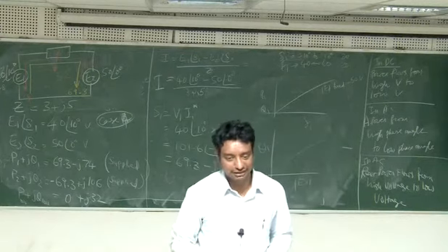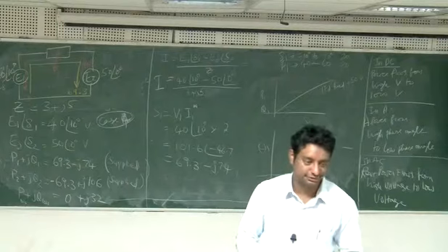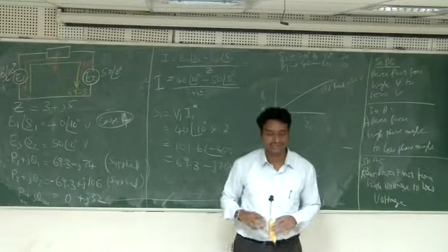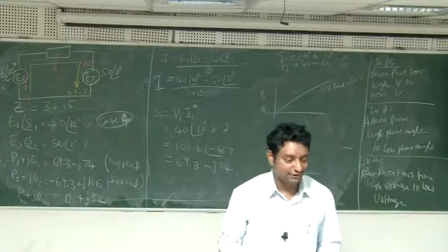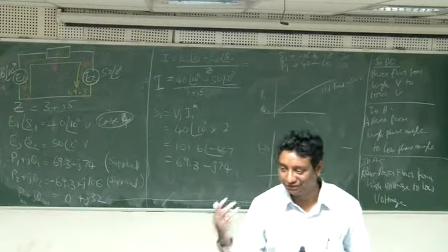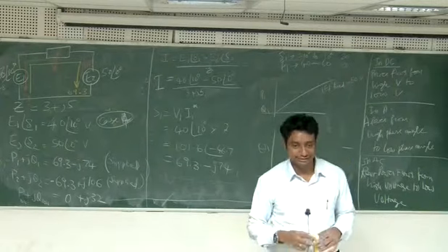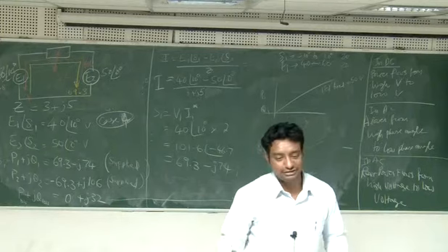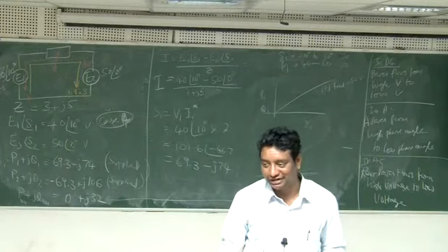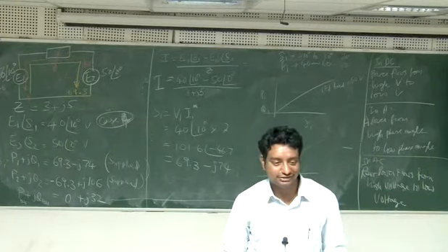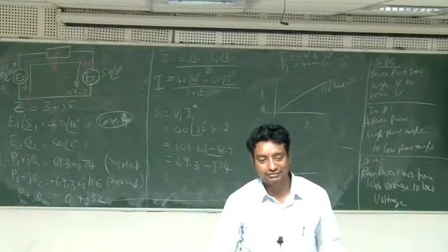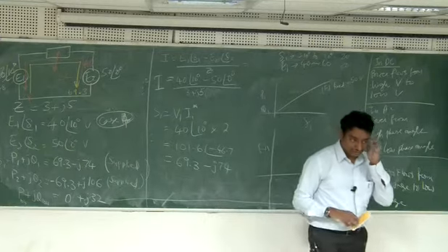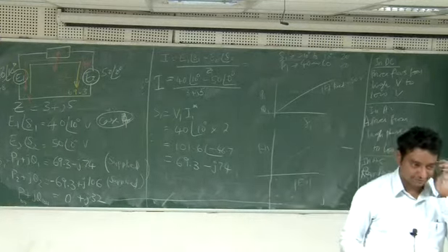The cost is mainly driven by active power because you are burning fuel to make active power. Whereas in the case of a wind generator, we are not even burning any fuel, we are just extracting power from the wind wherever there is wind. So there the cost concept is completely different again. It is more about investment cost, and the weather data, how much wind is there in that place throughout a year, whether the wind is constant or varying. So the cost calculations are different in that case.